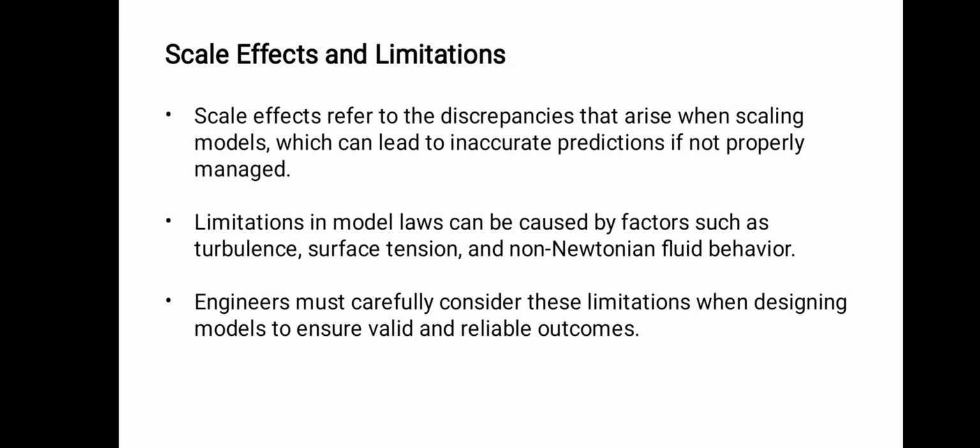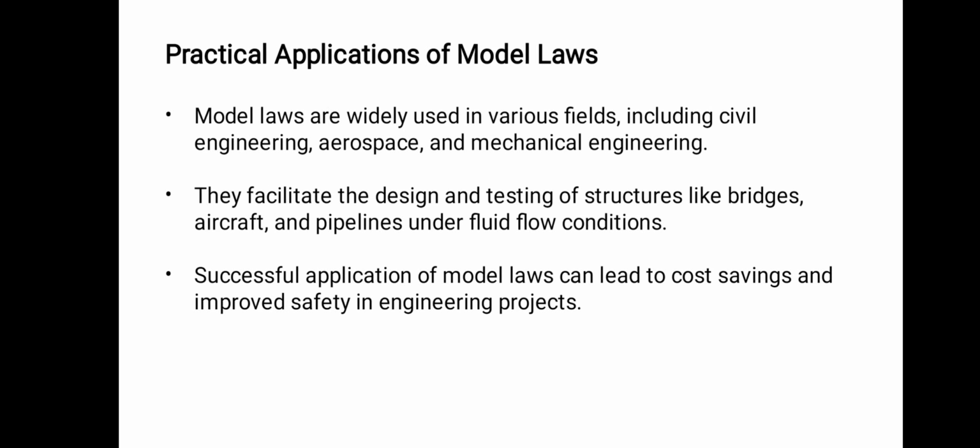Scale effects and limitations. Scale effects refer to the discrepancies that arise when scaling models, which lead to inaccurate predictions if not properly managed. Limitations in model laws can be caused by factors such as turbulence, surface tension, and non-Newtonian fluid behavior. Engineers must carefully consider these limitations when designing the models to ensure valid and reliable outcomes.